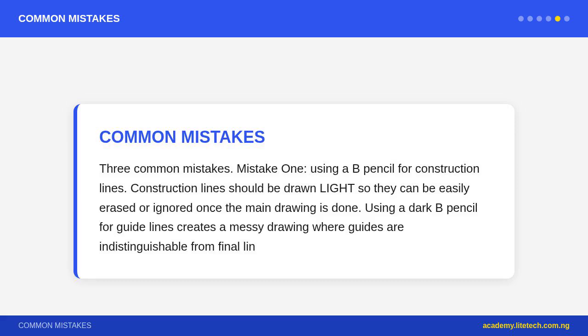Question 2. A student wants to draw a circle with a radius of 35 mm. List the steps using a compass. 1. Set the compass by placing the needle on a ruler at 0 mm and opening the pencil leg to 35 mm. 2. Mark the center point of the circle on the paper with a light pencil cross. 3. Place the compass needle on the center mark. 4. Rotate the pencil leg smoothly around the needle, drawing the circle. 5. Lift the compass without dragging.